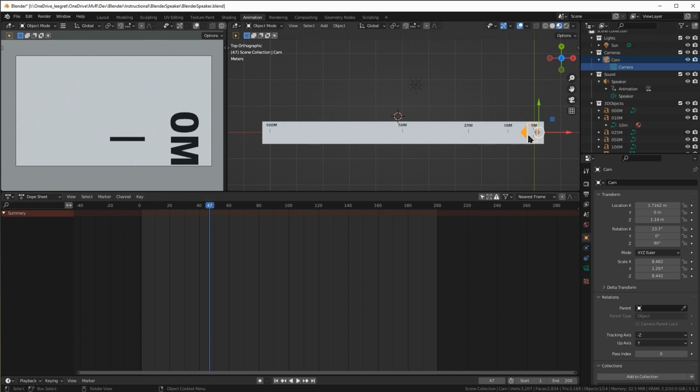So what we want this animation to do, and I'll move to the first frame in the animation, because really important in keyframing is making sure you're on the right frame. I'll click on this icon here to take us to frame 1, and we can see there's this lighter shaded piece here from frame 1 to 200. That's because our start frame is 1 and end frame is 200.